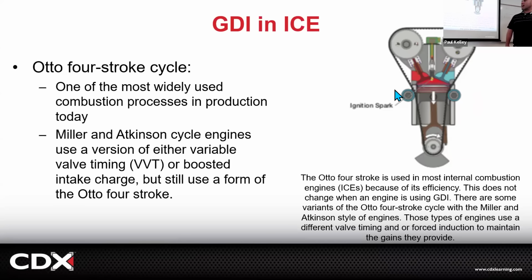So we eliminated that. Now instead, we have the engine go on the intake stroke. We can spray the fuel directly into the cylinder, or we could wait and spray it on the compression stroke. We could spray a little now, a little later, right? We're dealing with timing, a lot of different stuff when it's direct injection, all to increase the efficiency. And truthfully, we've gone away from the traditional 4-stroke. In the Atkinson, we're going to start hanging valves open longer.